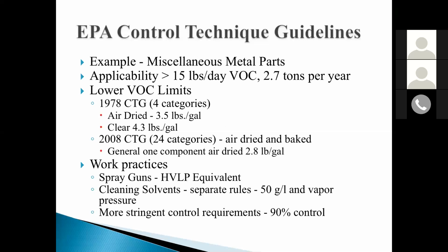I'm not sure about the rest of the country, but you're starting to see the new suite of regulations starting to recognize that VOCs can be liberated or generated when you have a reaction. The regulators are starting to recognize that, and you need to count that towards your VOC content. Again, that's more on the architectural side, and in some of the California Industrial Surface Coating Rules. I would believe it would be a trend in the future that there will be more recognition, because that's one of the pathways to get to lower VOC content: reactive coatings.